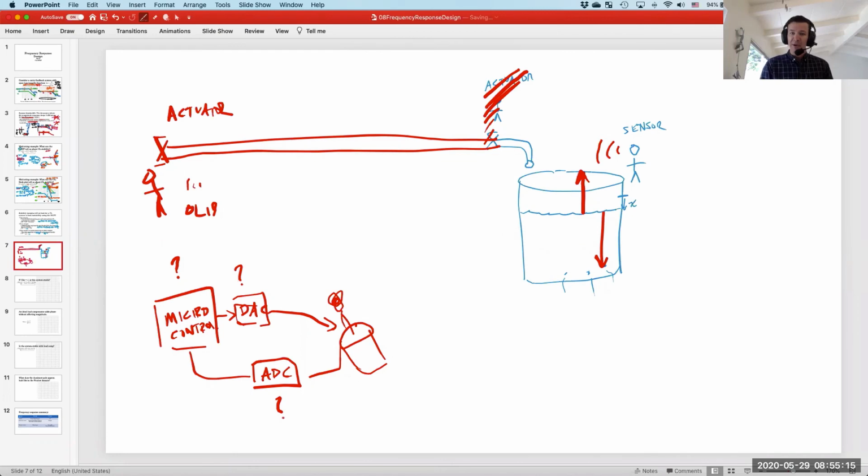Okay, so if your delay margin is 30 milliseconds, then you're fine, right? There is no way that an ADC, an Arduino, and then a DAC are going to combine for 30 milliseconds of delay. Not going to happen. But if your delay margin is 30 microseconds, or 3 microseconds, or 30 nanoseconds, then it becomes much more of a, we should probably start considering this. Because I'm not sure that an Arduino can read and write within 30 nanoseconds. I'm pretty sure it can't, actually.